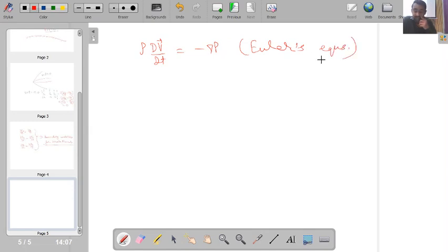So if I take Euler's equation, I can write the x momentum equation, particularly rho times vx into... let's write the x momentum equation for the steady flow situation. For steady flow, the time term will be equal to 0, so I will have only the spatial terms.